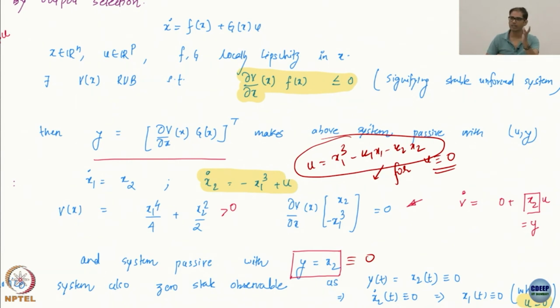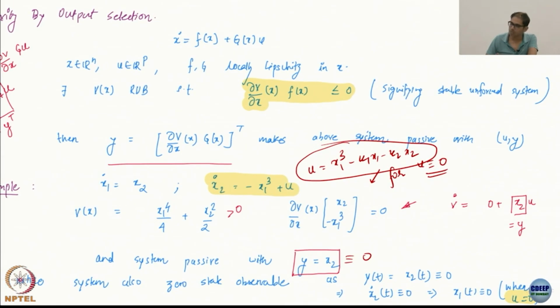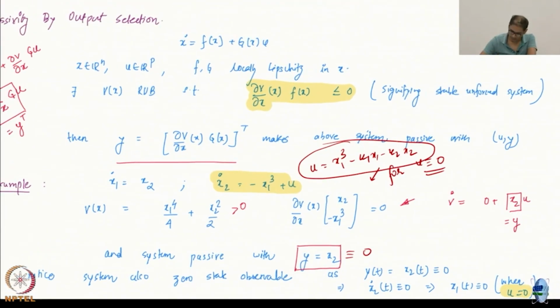This is how we keep manipulating early Lyapunov candidates. This is a pretty good idea. Okay, great. So V dot turned out to be 0 and V was radially unbounded. What does it mean? That the unforced system is stable, or uniformly stable, in the sense of Lyapunov. Okay, great.